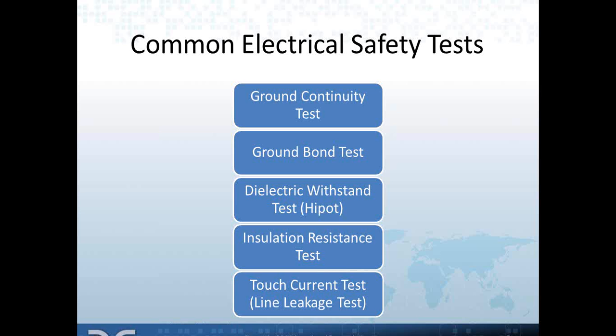The insulation in question is used to separate the power line circuit from low voltage circuits, isolated power supplies, the chassis, or the case of the product. This insulation prevents current from an ordinary household outlet or any power source, which is almost an unlimited power source, from becoming hazardous by finding a ground path with something that is not meant to be a ground path.